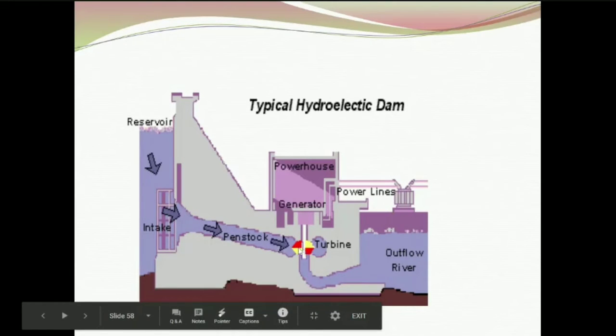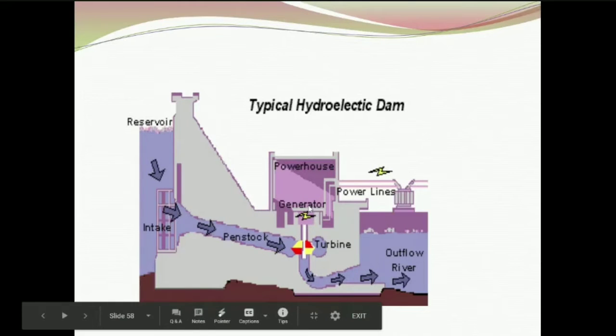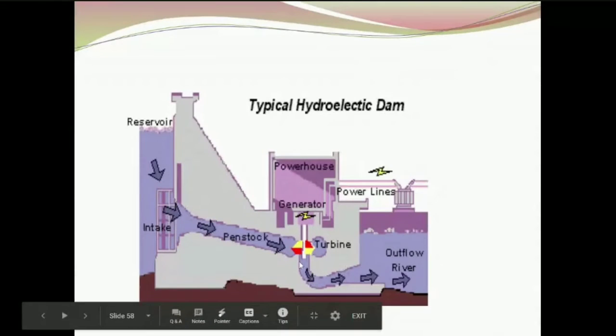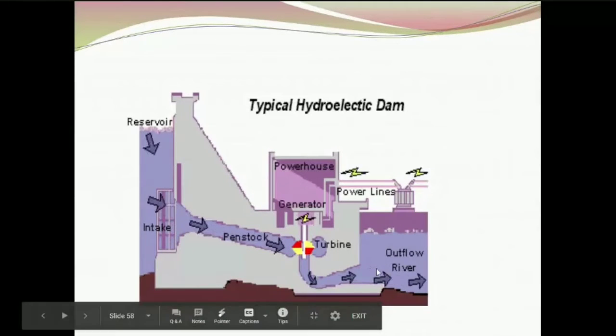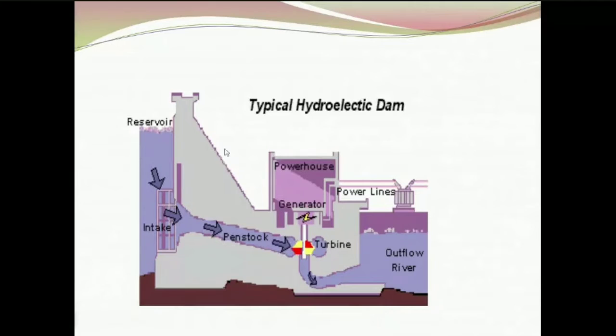When the turbine rotates, the mechanical energy produced by it is supplied to a generator by coupling the turbine with the electric generator. Hence, the generator produces electricity as per Faraday's law of electromagnetic induction. Water after use from the turbine goes to the tail race by means of a tube called draft tube. This is the approximate working of a hydroelectric power plant in brief.